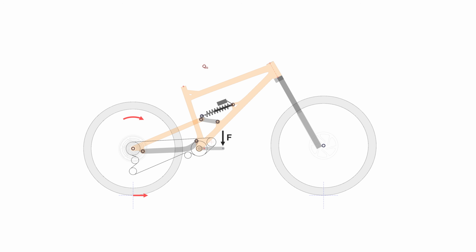But at the same time, the tire knobs bend forward, which means there must be a forward-pointing reaction force acting on the contact patch. When the torques in the wheel balance, this force is transferred through the spokes to the rear axle and pushes the bike forward. Since this force vector is parallel to the ground and does not pass through the center of gravity, it creates a moment that tries to rotate the bike backward. The wheels resist that rotation, and as a result, weight shifts from the front to the rear of the bike.